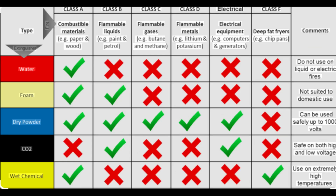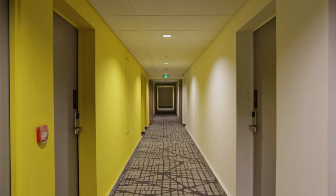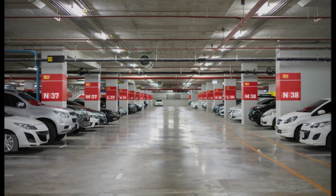2. Hazard classification. Based on NFPA, guest rooms are light hazard, corridors light hazard, kitchens ordinary hazard group 1, storage rooms OH1 or OH2, parking and basement parking hazard category. Hazard classification defines sprinkler spacing, water discharge density, and design area.